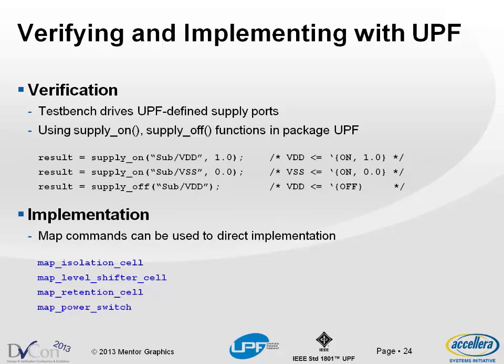Verification, just to add a little bit more detail, involves typically running simulation or some kind of dynamic verification. Of course, there's also static verification. I won't touch on that here. But when you're running dynamic verification, what you want to do is set up those supplies so that you can observe the effect of turning the supplies on or off, changing the voltages, etc.